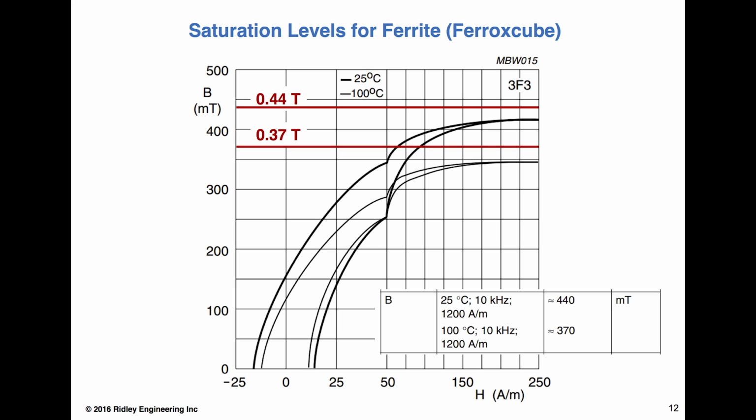They stored a little negative current and held it there, ready to re-switch. So you can do the critical conduction mode if you like. You can let it go negative and use the current there as well if you like. There are many, many different flavors of getting that zero voltage. And the terminology between critical conduction and discontinuous mode, they're very similar, just small differences there. But the Vicor one was interesting in that they let the current go negative and clamped it to that negative current.